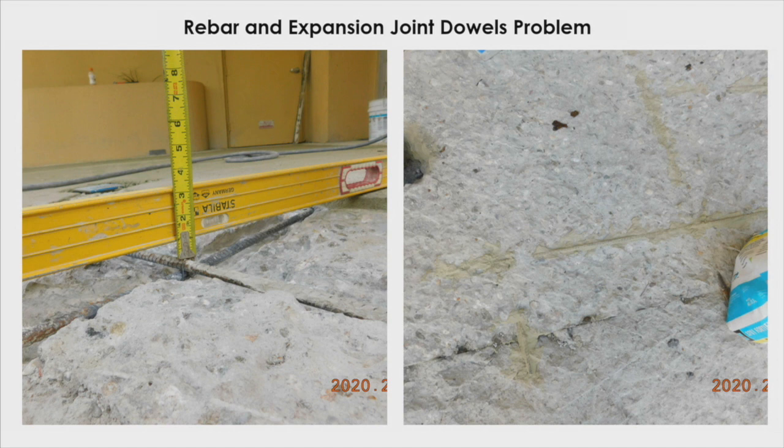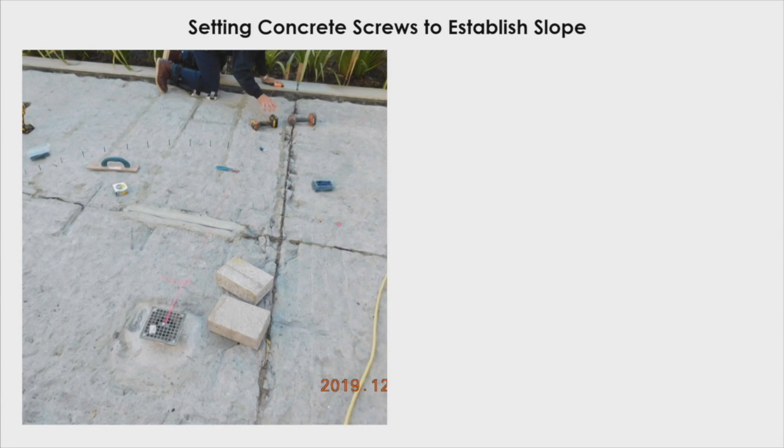So the ones that were exposed, we had to treat according to the manufacturer's recommendations for the high strength mortar, treat it with their thin set mortar to coat it. So again, that helps it not be susceptible to corrosion.